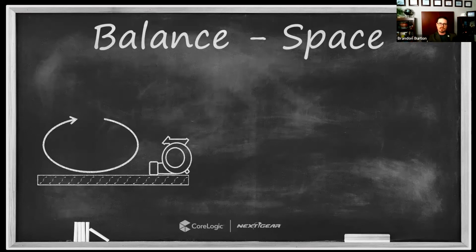Okay, so that was over time and watching our humidity over time. Let me introduce the concept of balancing for space. The purpose of air movement in a drying environment is really twofold. There are 2 primary reasons why we have air movement. The reason for air movement is to provide circulation throughout the space, right? To ensure that air at one area of the space is representative or similar to air in another area of the space, as long as we're talking about inside of our drying chamber.